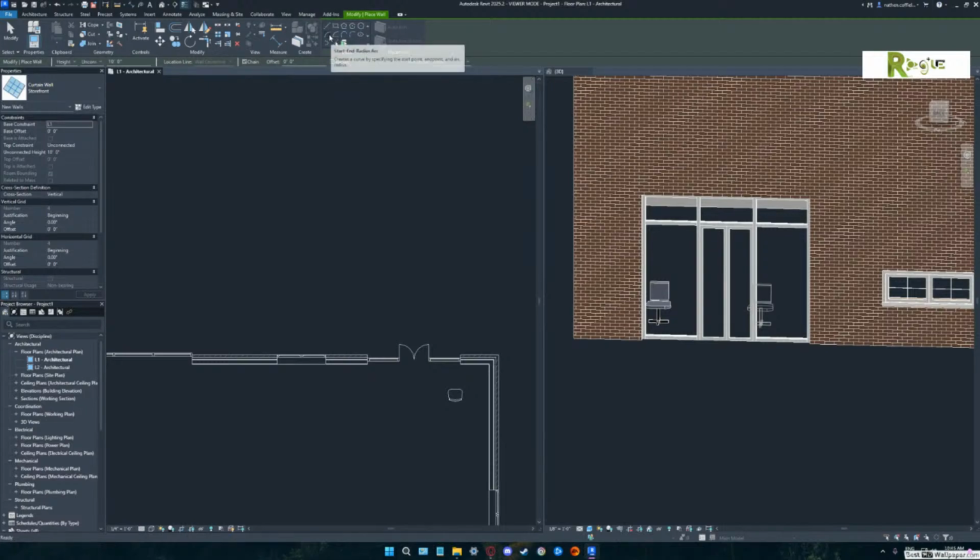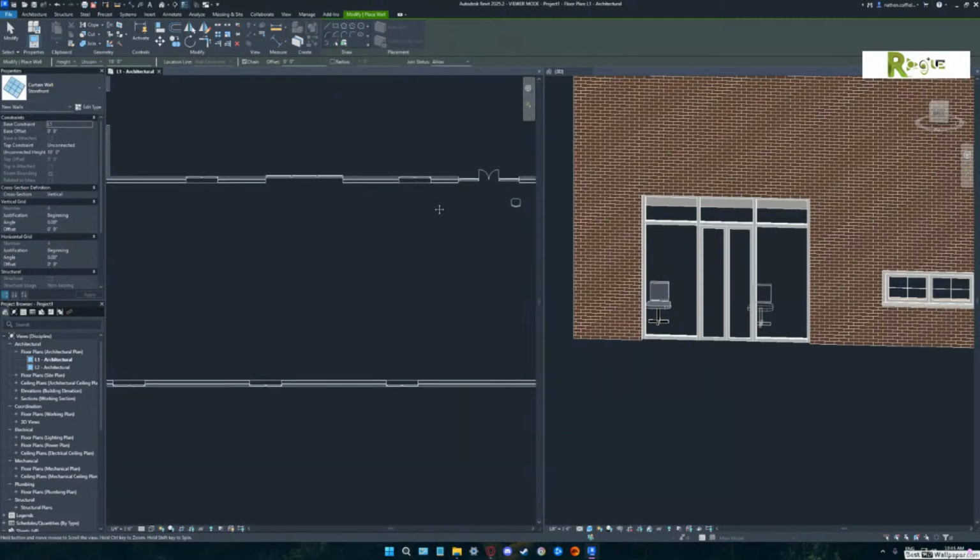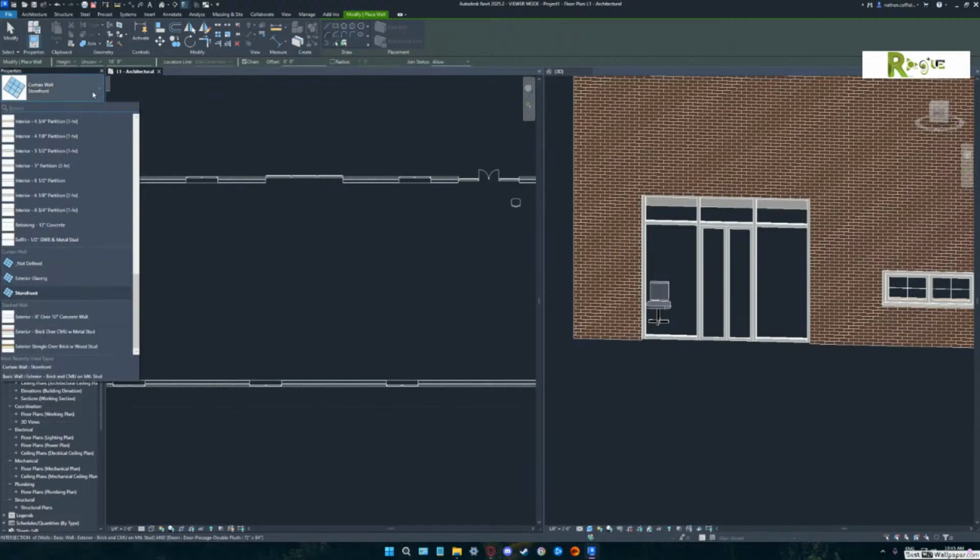The first one works good. You'll play with them all. This is a 3-point curve. You draw the start point, the end point, and then the amount of curve distance. Now, here's what's happening. What did I tell you Revit does? It remembers the last kind of wall you were drawing. I'm drawing a curtain wall storefront, and the curtain wall storefront is not going to show the arc.